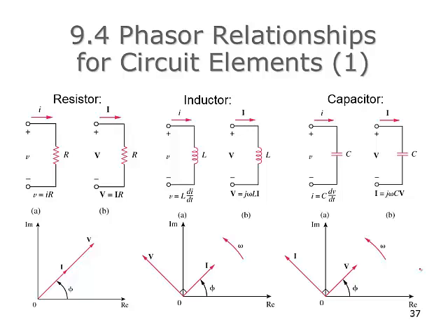And what that looks like in the complex plane basically is saying if you have a resistor, well, in the phasor domain, phasor V and phasor I are related by phasor V equals I times R. It's the same phase, but a different amplitude, right? You have to take I, multiply it by R. So the V vector is going to be probably bigger than the I vector, but it's going to have the same phase. And they're going to be spinning around in phase with each other. If you've got an inductor, though, the voltage is going to be j omega L times the current, and that j is pushing a 90-degree phase shift ahead of the current. So the voltage is going to be leading the current by 90 degrees, right?